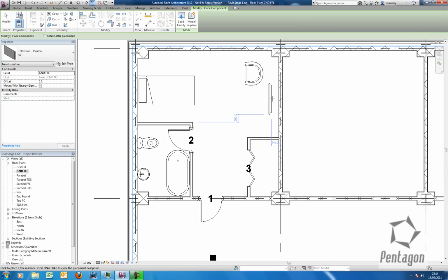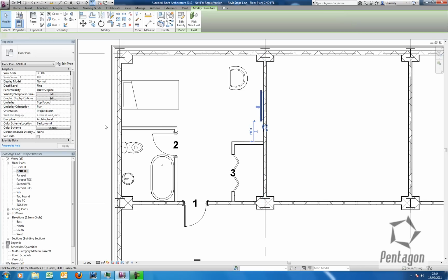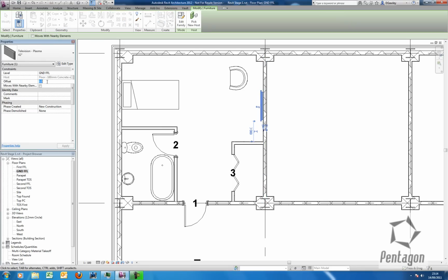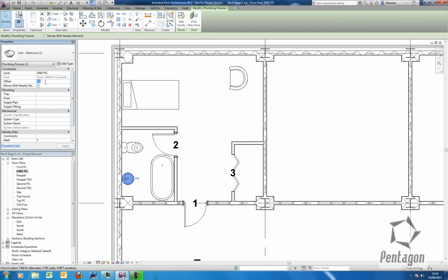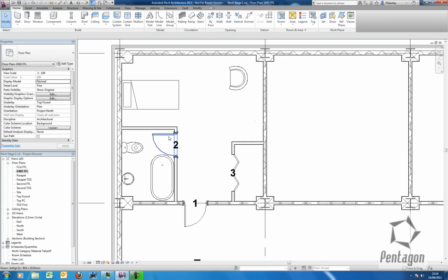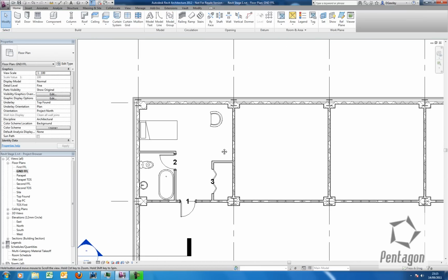Okay, so we're kitting out the room again. Hit the space bar, the tie-in. So I'm just going to change some properties in here because I want that offset to be 1.5 meters off the ground. I need my sink to be around 1 meter off the ground. Again, we can apply that in here. My door position, again, we can change these. If you're familiar with Revit, you'll have a good understanding of this. So we've got the typical room layout that I want.